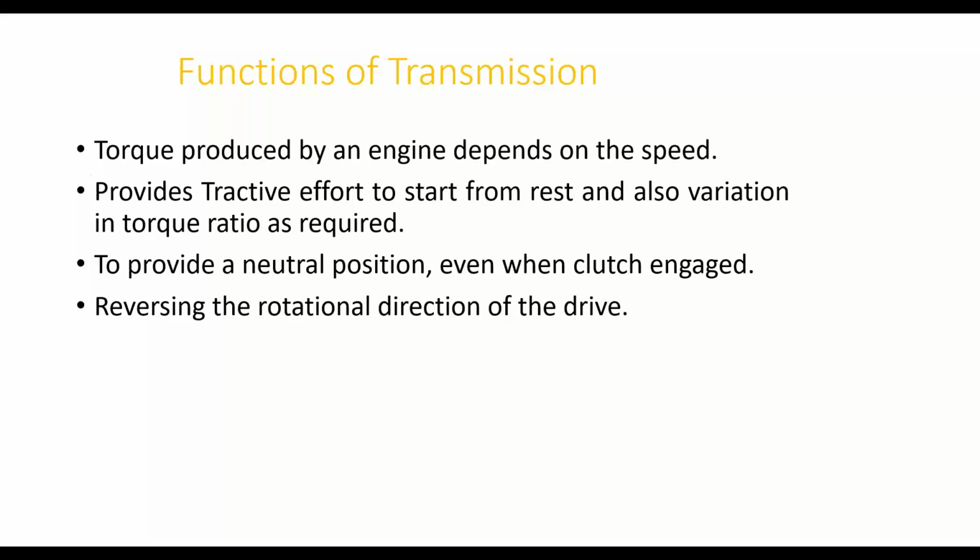So if you put it in first gear and leave the clutch, what happens? The engine is directly coupled to the rear wheels, so the vehicle starts moving, or with a jerk it gets switched off. If you want to keep a vehicle in the idle condition, there should be a provision. That provision is provided by the transmission system. So there is a particular position in the gearbox.